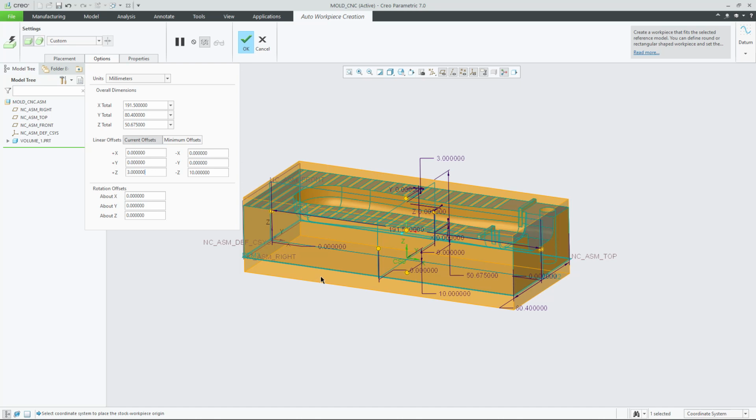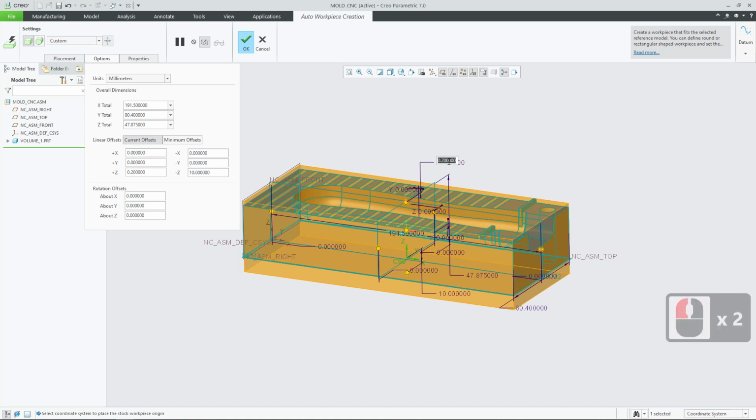So often when you're provided with a billet of metal, normally, it will have been cut on some kind of industrial saw, and the saw blade can wander, it can produce non-parallel faces. So having this as an incredibly small value, let's make it 0.2 of a millimeter, that can be quite dangerous in that if the person that's cut this block has done a bad job and the block wanders in and out and in and out, then that margin for error can be quickly used up. So let's put 3 mil back on there.